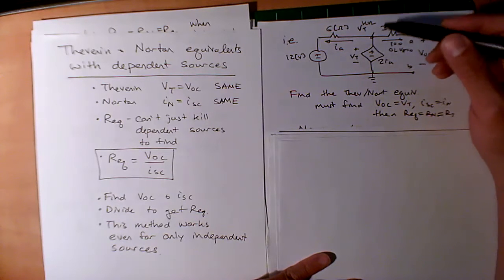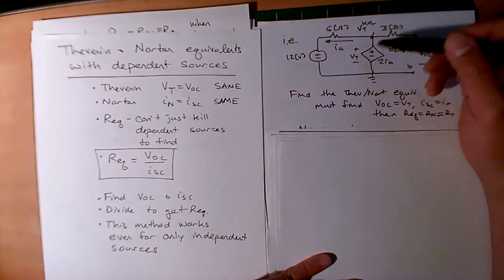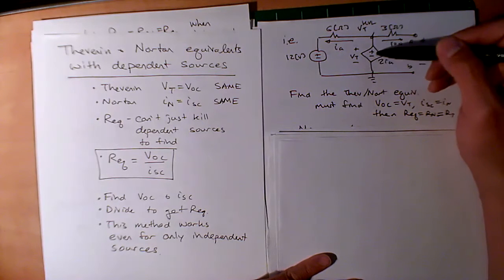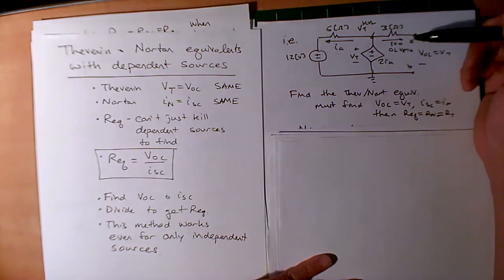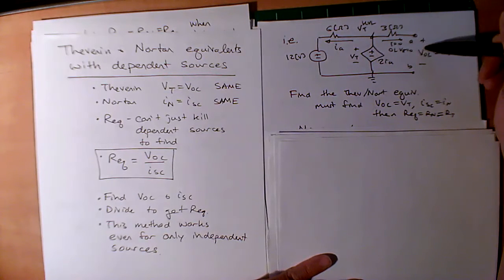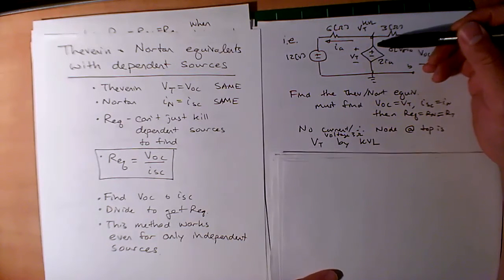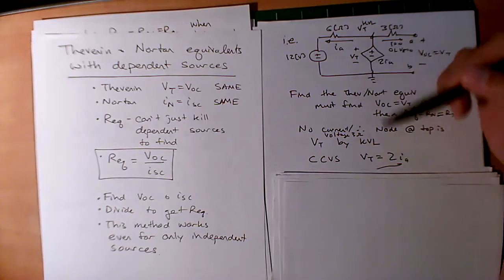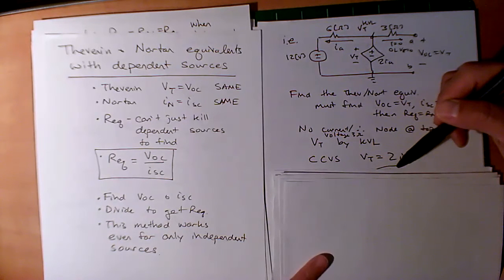The other thing to note is if I had current flowing through this current controlled voltage source, it has no choice but to go to the left because this is an open circuit. So actually these 3 elements are all in series. Huh, that's nice. So that will help us peel apart this onion layer and solve for this voltage. Okay, so from the current controlled voltage source, I actually have the equation VT equals 2IA. Yes, no problem with that, okay?